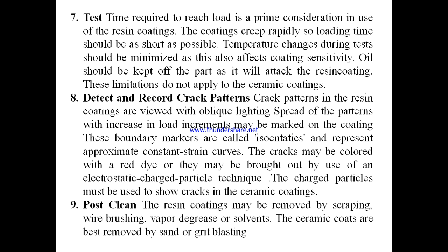Then you have to test. Time required to reach load is a prime consideration in the use of this resin coating. The coatings creep rapidly, so loading time should be as short as possible. Temperature changes during test should be minimized, as this also affects coating sensitivity. Oil should be kept off the part, as it will attack the resin coating. This limitation does not apply to ceramic coatings.